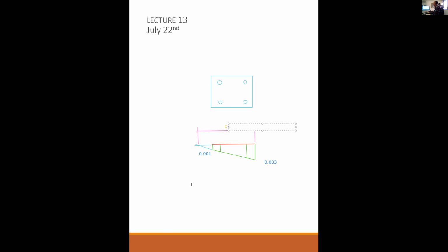Okay, and that's perfectly fine. It's just a measure of where we go from 0.003 to 0 strain, is little c. And it's okay if it's outside of the column itself. Little c can be greater than 24 inches in this case, if the column's 24 inches wide.